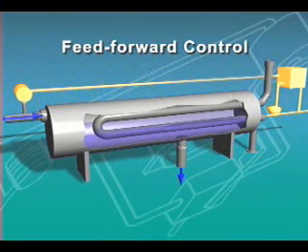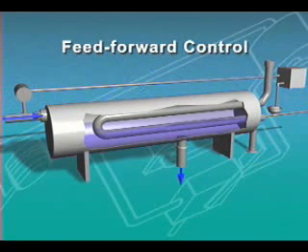If a difference is noted, the controlling element sends a proportional control signal to the final controlling element, the gas supply valve of a gas-fired heater, which then increases or decreases the temperature of the fire tube. The result of this feed-forward control is that the temperature of the controlled variable, in this case the temperature of the heated water in the vessel, will be consistent.